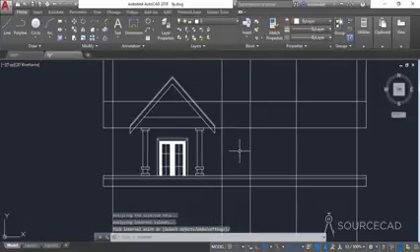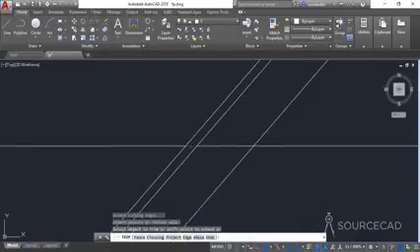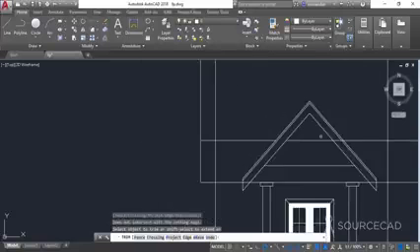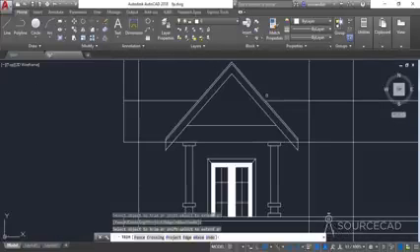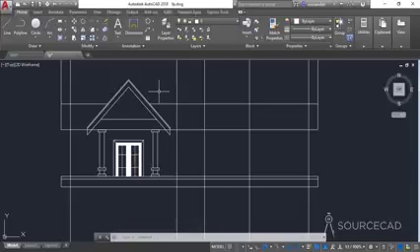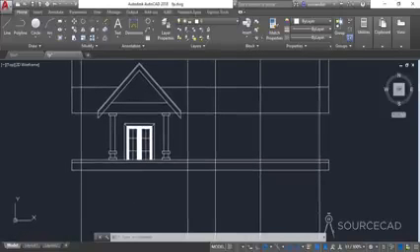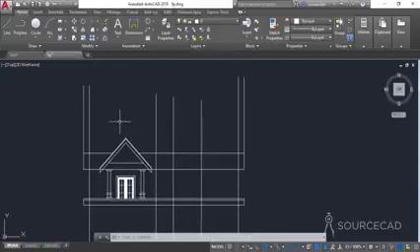So a door is almost prepared. Let's now clean this part of the drawing. So I'll go to trim, press enter, and let's clean this one. All right, so that's now properly cleaned. We have this clean drawing here up to this point, and now we can add the final details to this drawing. And before doing that, actually I just prefer to keep my drawing clean, so I'll remove all the unnecessary details from this drawing that are not required.